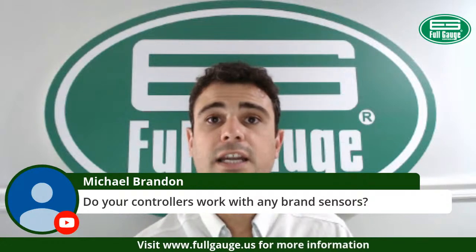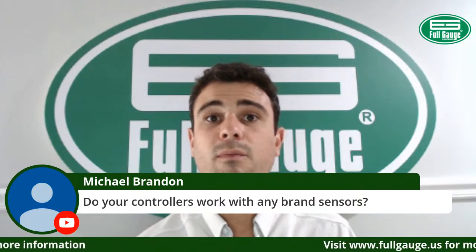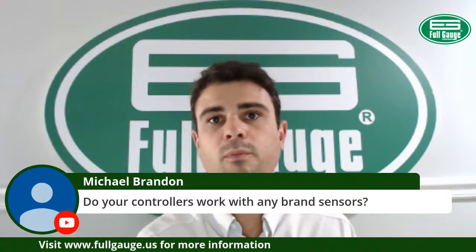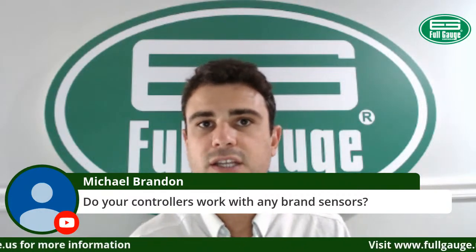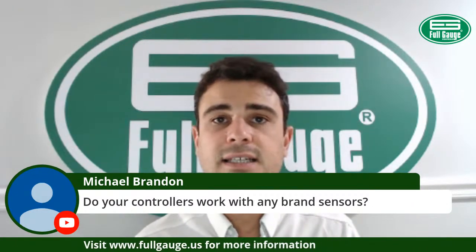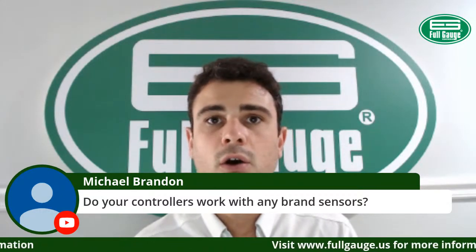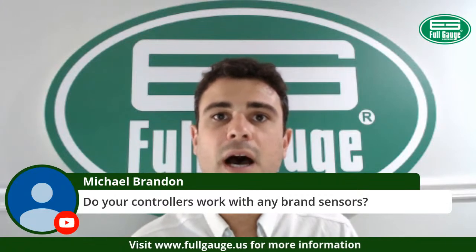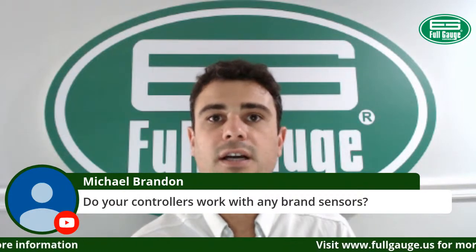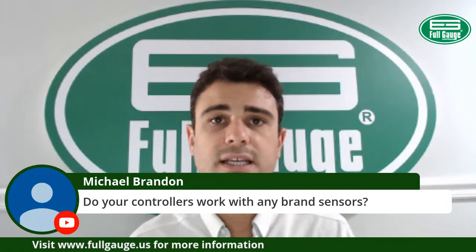But our controllers provide you the offset option, which allows you to adjust any temperature deviation that might have been created by a different sensor. Another alternative is to strip the tip of the sensor and connect our tip. If you don't want to rerun the sensor on the equipment, you can just cut the tip out and wire our Full Gauge sensor tip back in, and you're going to be using our sensor in that case.